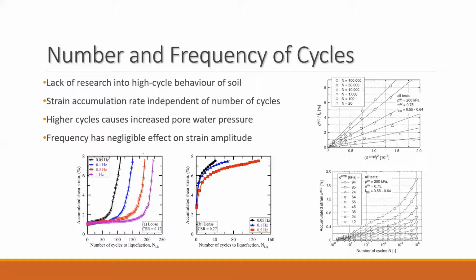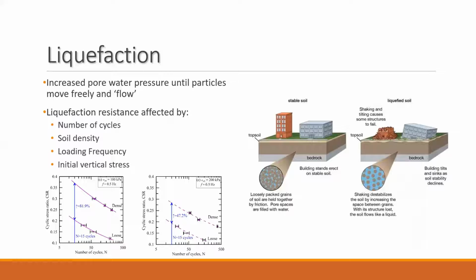Loading frequency is shown to have a negligible effect on strain amplitudes of soil samples tested. However, it has been found to have a significant effect on the liquefaction resistance of the soil. Liquefaction is a phenomenon where the pore water pressure within soil is increased to the point where the soil particles can move freely relative to each other, and is commonly caused by the ground shaking from earthquakes.